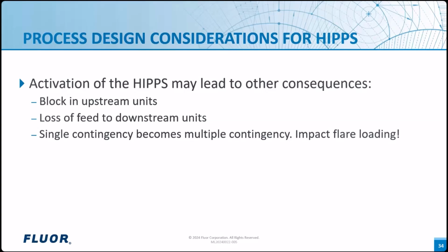For example, a HIPPS event could also result in reverse flow when it trips a pump discharging into a common header. These knock-on effects can impact flare sizing and should be considered.